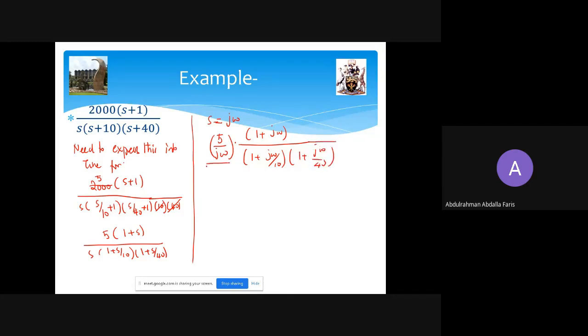So we know how to plot this, that, and that. This is a real zero, and these two are real poles. So first, you can say corner frequencies. For this zero, the corner frequency is where the denominator of omega is 1, so omega is equal to 1 radian per second.